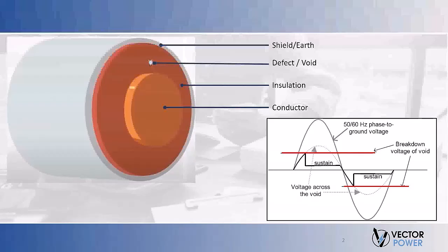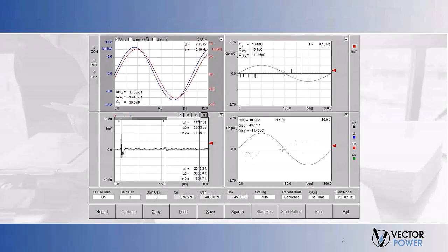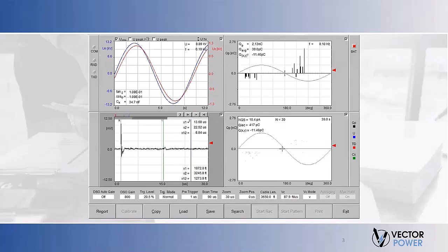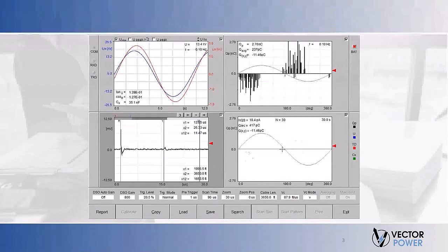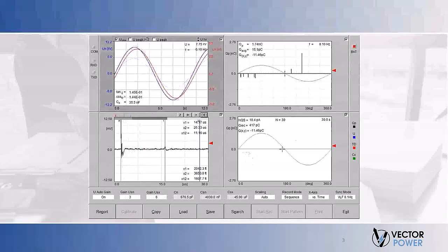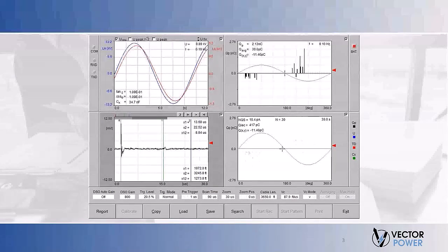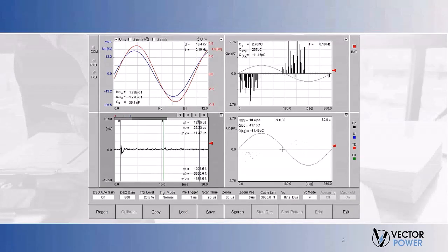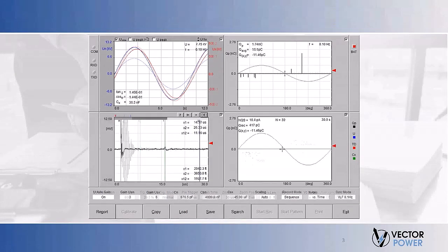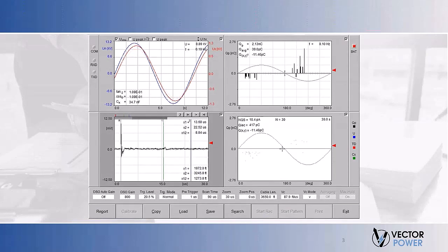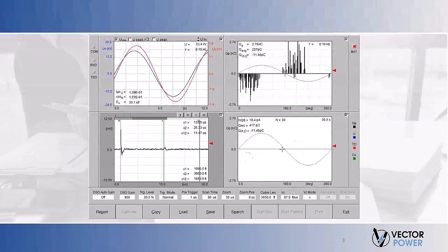The defects may be located entirely within the insulation, along the interfaces between different insulating materials, or along the insulation surfaces, such as terminations or potheads. The characteristics of partial discharge depend on various factors, including the defect's type, size and shape, and location, insulating material, applied voltage, and the cable temperature. These characteristics can change the magnitude or frequency over time.